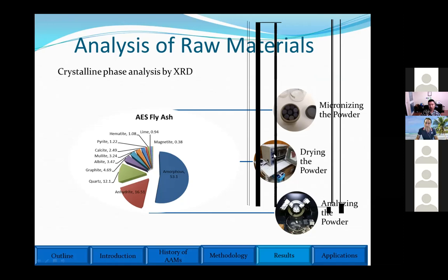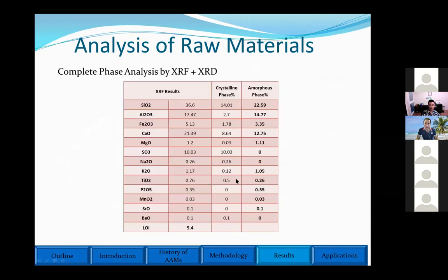Another problem for drying the powders was that we couldn't use heat, because heat would change the property of our concrete and we didn't want that. So we needed a lot of hours in this vacuum oven, which is a specific type of oven. It was hard to prepare samples for XRD, but the result was fantastic.